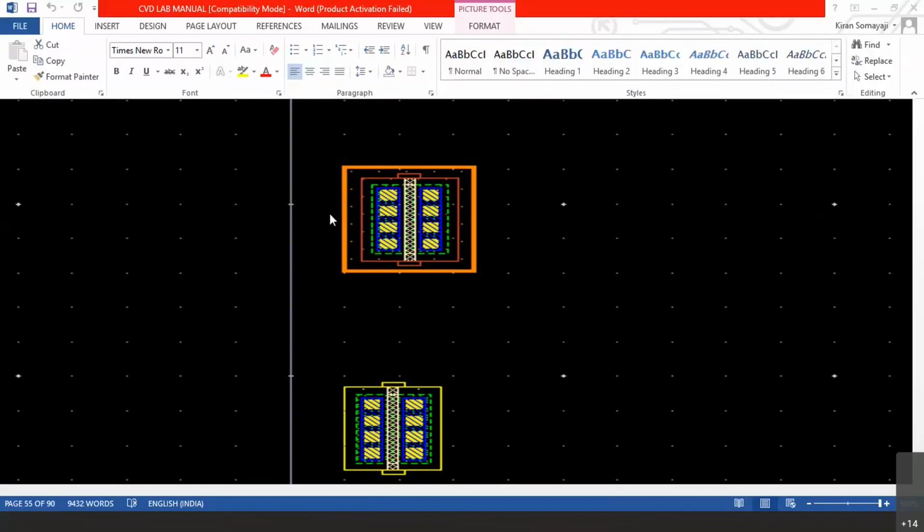You can see that the device is completely geometrically symmetric, means whichever way you take it as source or drain, it is immaterial. Whether you consider the right side as the source or the left side as the source is immaterial. Only when you make connections, whichever is connected to the VDD, in case of P MOSFET, you will call it source. Whichever is connected to the output pin, you call it drain. Otherwise, right now, they are physically identical and interchangeable. After we make connections, then we define them as source and drain.